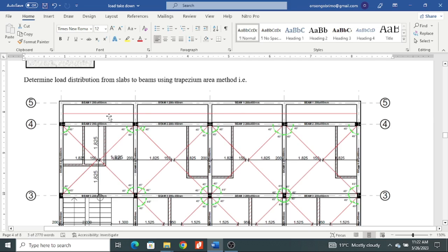Now these are structural systems that you should analyze carefully as the engineer, because once this load gets to this beam, it is not just lying on air, it is being supported by a certain beam here and another beam here. Therefore it will distribute half of its load here and half of its load here as point loads.